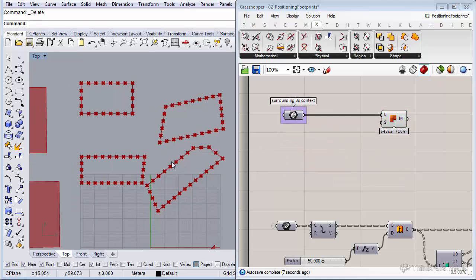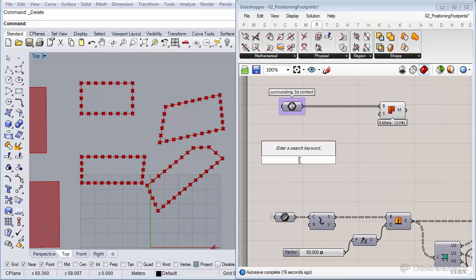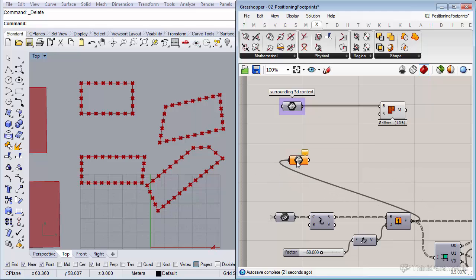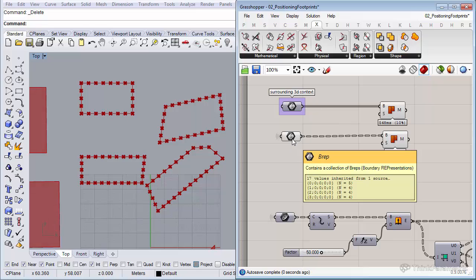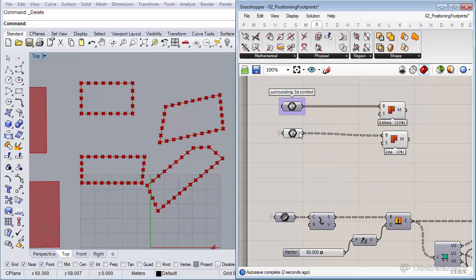The next thing, because we also want to include our 4 buildings for the views, let's insert a B-rep, and those come from the ones we just generated. Let me also set the wire to hidden. And we're going to do the same thing: copy this component over and transform our 4 buildings, or our 4 facades, to meshes. Nice.